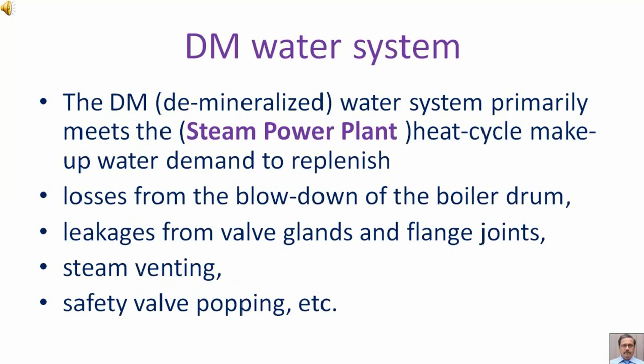DM water system. The DM, that is demineralized water system, primarily meets the heat cycle makeup water demand to replenish losses from the blowdown of the boiler drum, leakages from valve glands and flange joints, steam venting, safety valve popping, etc.